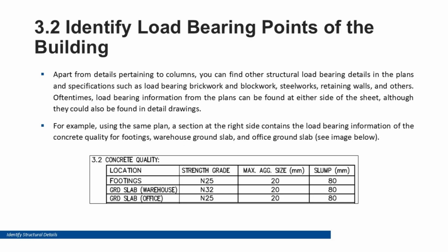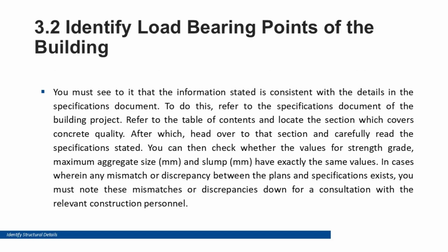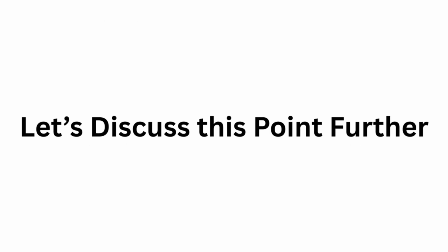Load-bearing details may also be found in the specifications, for example, concrete strength grade, slump requirements, reinforcement anchorage, and minimum cover. Identifying load-bearing points ensures construction follows engineering intentions and maintains structural integrity.